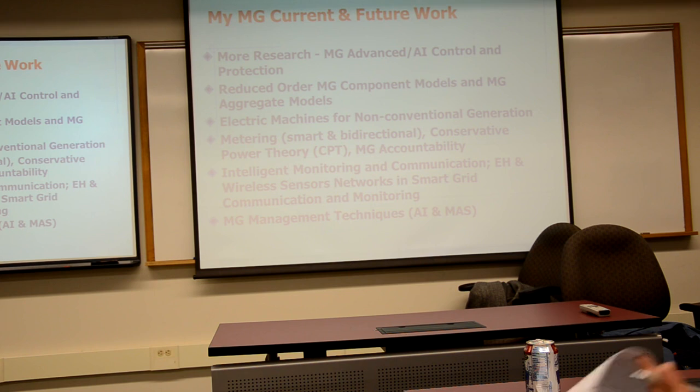Because the idea was that you interconnect the system and get what is named the infinite bus. It's very stable, with a very large inertia, and a large number of loads that can connect and disconnect, and a large number of generators that may have malfunctions and disconnect from the power system. Power plants usually have at least one third of the capacity in backup.